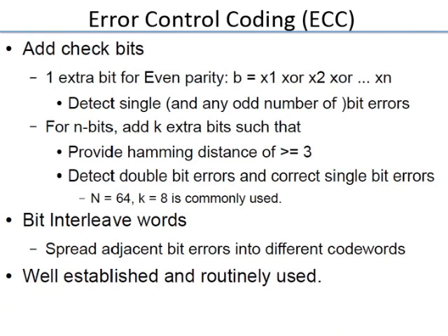Any questions? Is only a single parity coding system being used, or any more complicated coding system? Basically, what is usually used is called SECDED, single error correction, double error detection. But for something like Flash and so on, more complex coding is used, like Reed-Solomon codes and other codes for burst errors. Similarly for hard disks, of course there we are not dealing with soft error problems, but you will have failures, or bursts of bits can fail, so you have to use more sophisticated codes.